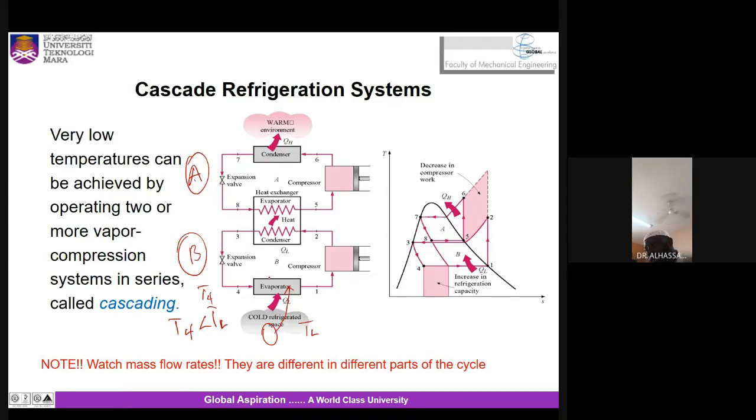Okay? So when the fluid enters this region, it will be absorbing the heat from here. In other words, its temperature will be increasing gradually until it exits at state 1. So during that stage, we follow this trend. It goes like this, state 4. So the fluid is being heated up, so more vapor is forming, you understand me? Until eventually the fluid is saturated vapor, then it exits at state 1. At this state, the fluid is compressed by the compressor. So there is compression, isentropically compressed.